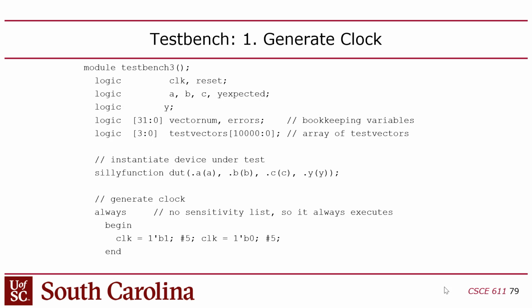You might say, well, wait a minute, then how does the clock work in real hardware? The only way to do it that I know of is through a crystal oscillator. Or maybe you could do an oscillator with inverters connected in a ring. What was it? A ring oscillator. You could build a ring oscillator. But generally speaking, the real clock is generated through a crystal. But this is the virtual clock.